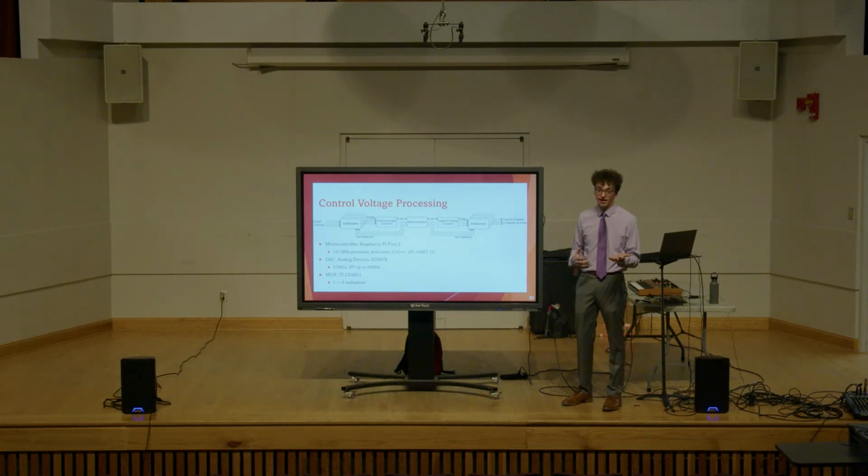So one in this case would be the control voltage processing, and then the other would be MIDI processing at the same time. It programs in C and C++, which I am proficient in, and is also a very fast programming language to run. And then it also includes peripherals for SPI, UART, and I2C communication protocols for whatever digital devices I will end up using in conjunction with the Pico.